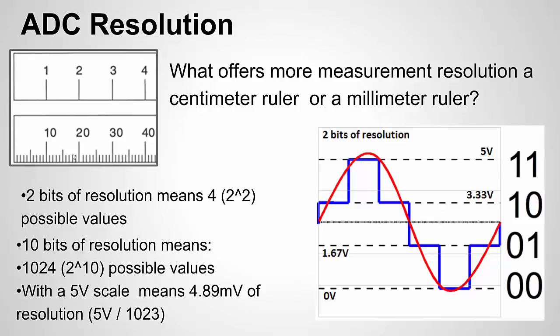But if I'm using millimeters, and it's a little less, let's say it's 18 millimeters, I can say 18 millimeters instead of 20, or 2 centimeters. Or I could say 22 millimeters. So you're getting more information about the true value of the signal. More resolution, the better, right? Now, there are limitations, and I'll probably talk about this more, but you could have very high resolution, but if you have poor accuracy, not all of the bits may be useful. And vice versa, you could have ideal accuracy but low resolution, and you're not going to be able to represent the true value of that signal.